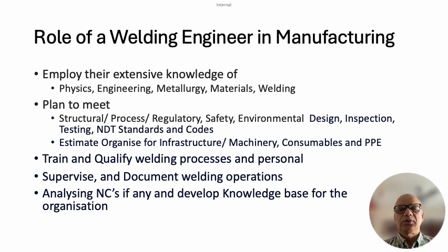If not, the non-conformance is required to be reported, and the repair activities as permissible by codes and standards are carried out. And then you document all these things, and if there are any non-conformances, not only in the welding but in distortion or in the dimensions, they are required to be reported. If fixturing is required, that is analyzed in stage 2 in the plant to meet the structural integrity, you normally design a fixture, or for a process you have a fixture.